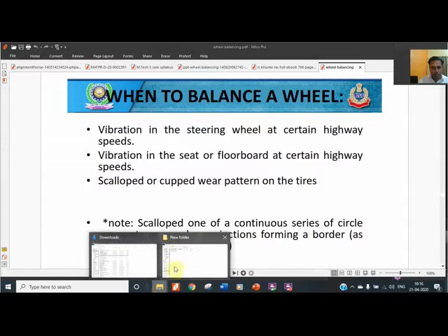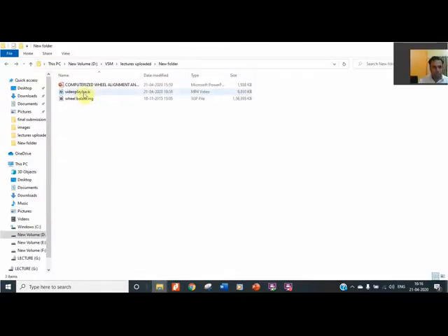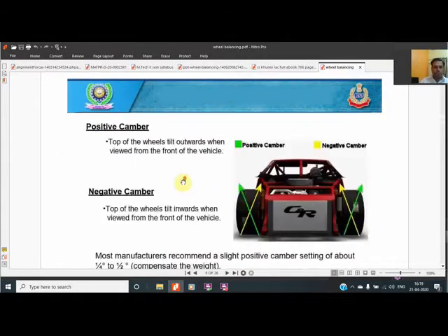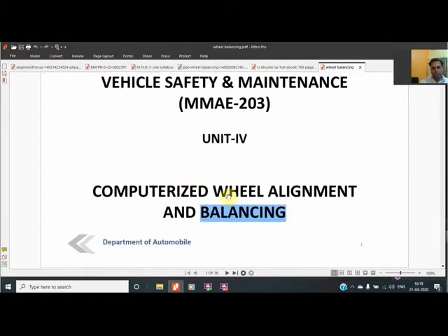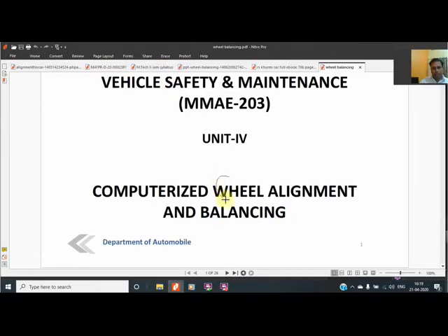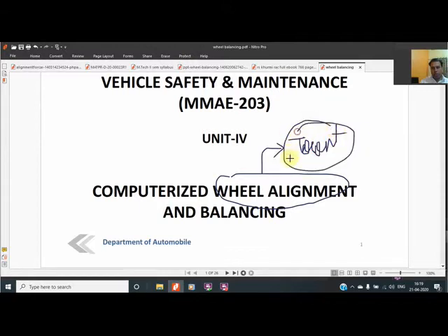I will show you some videos also, because some videos are recorded by me. So we will cover this topic and we are going to start with it. We are going through the important terms included for wheel alignment, because wheel alignment is a different thing. For that, the steering geometry angles are dealt with, and in most cases the angle dealt with is the toe-in toe-out. When you go to a shop for wheel alignment, they generally change the toe-in toe-out angle.